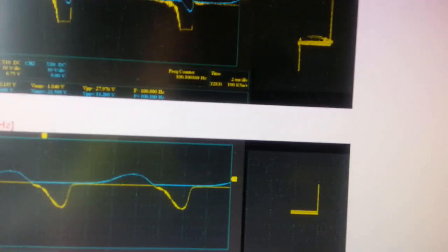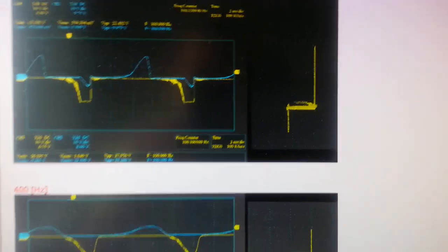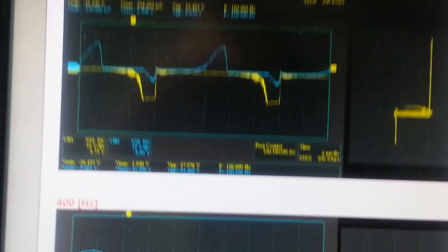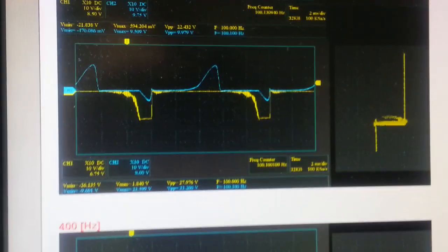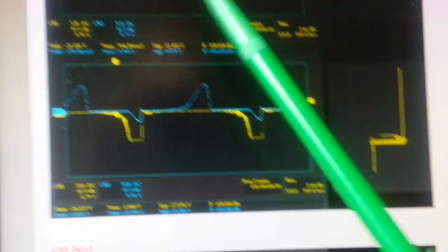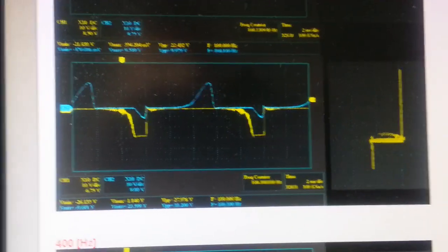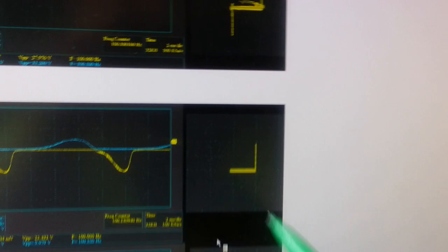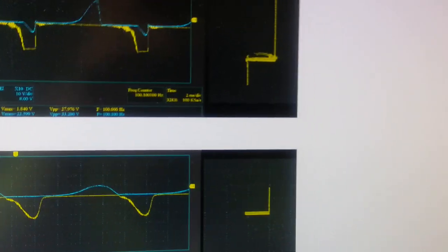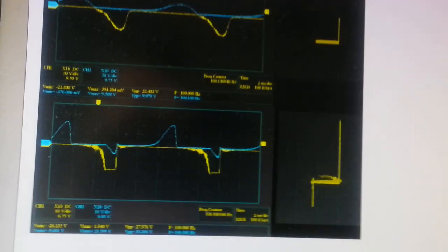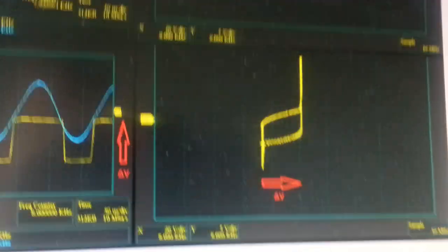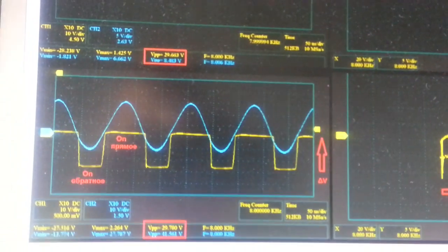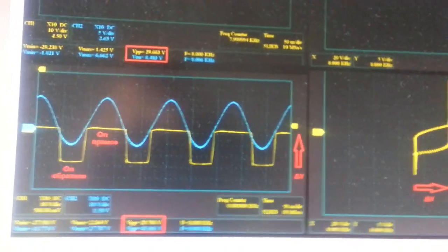So I guess at small frequency we can just remove this strange effect. But in my case, smaller frequencies are not good for the system, because the transformer is not capable of multiplying small frequencies. So in that case we have strange shapes. But anyways, the key moment is that at small frequencies we have patterns similar to the textbooks. If we increase the frequency, we're going to have this hysteresis curve, which was a bit surprising to me.